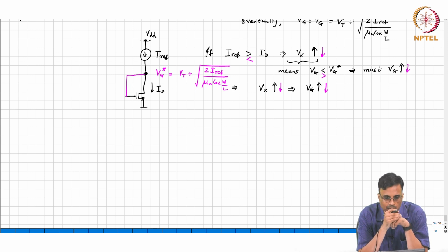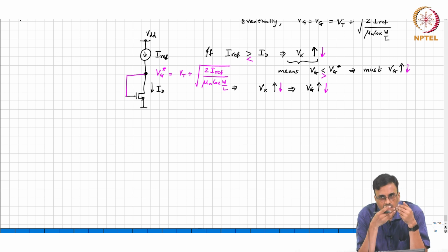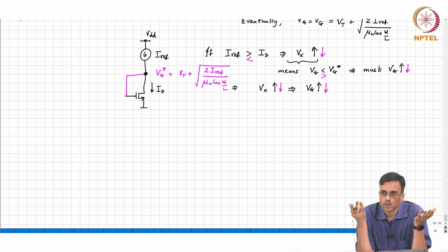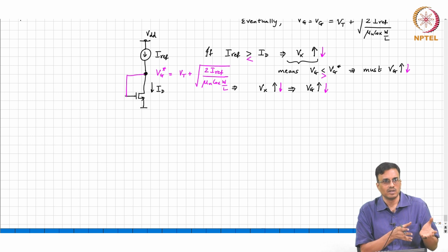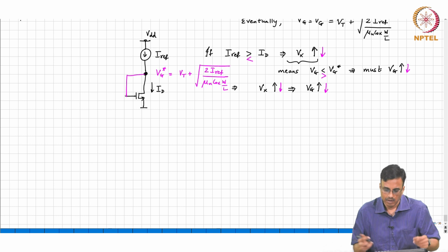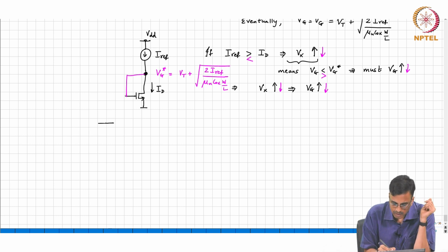1000 devices on the same IC, it turns out that the threshold voltage of all the devices is the same, at least to first order, right. It may not be what you want, but it is all the same. So, then what can you do? You can use one transistor to find the magic voltage and apply the same magic voltage to another transistor.